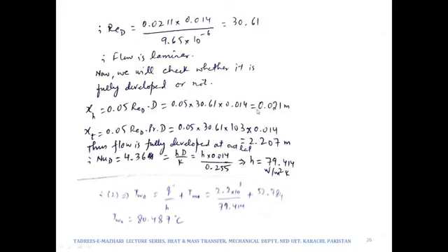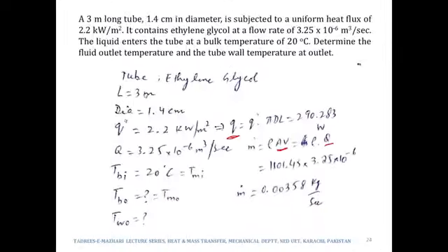It means that from the start of the pipe till 0.021 meters, so this would be the length that the flow will take so as to get a uniform velocity profile. Now what is the length of the pipe? The length of the pipe is given to us as 3 meters, right? So this length 0.021 meters is less than 3 meters.